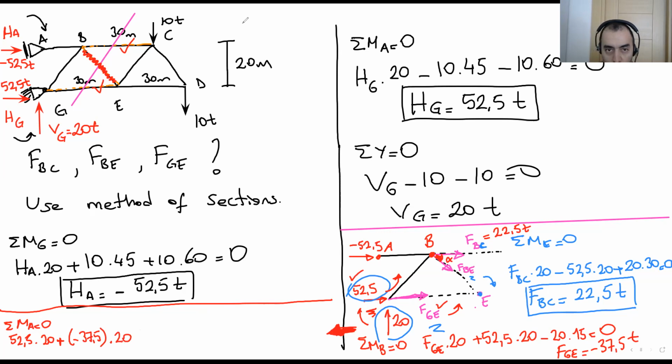I need to calculate the vertical and horizontal component of FBE. Horizontal component of this FBE has a 0 moment on point A. So what I need, only vertical component. FBE rotates the system in the negative direction according to my initial assumption. So minus FBE.